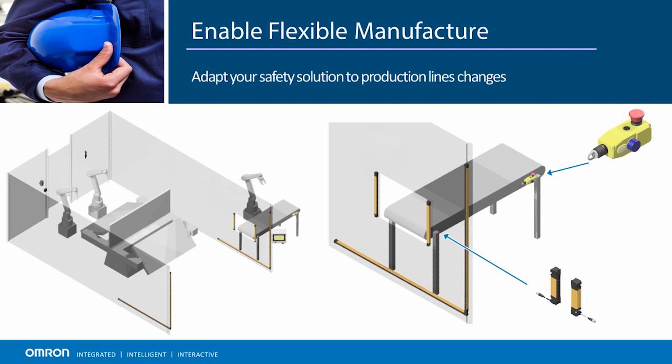Either scenario bears a unique challenge for safety systems, as flexibility is required to modify an existing system as well as make it scalable so the application can grow according to the production demand. An example of this would be if now we decide to add a conveyor system to our application, which involves new risks that need to be addressed. As part of the solution, we'll need to add a rope switch and a pair of light curtains and a remote node to connect the new safety devices.